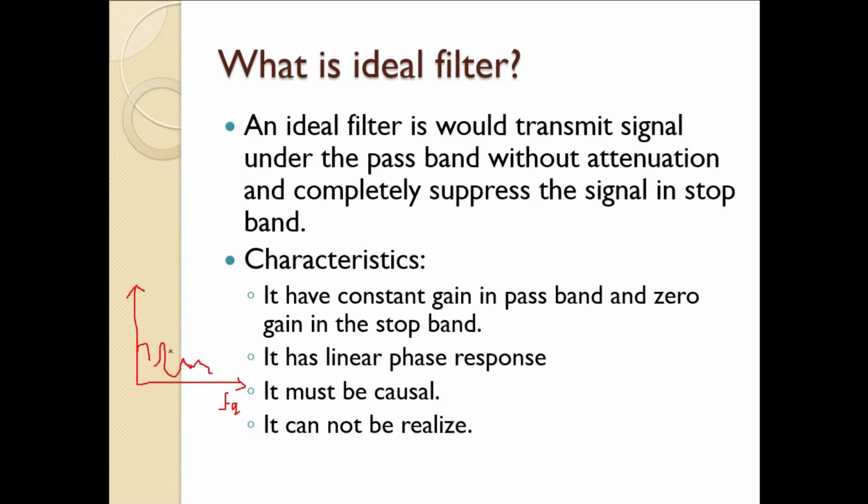In this range of frequency, we can cut off. For example, if the frequency is more than 5 Hertz, I don't want it. So I can set the frequency here and it will cut off like this. After the frequency of 5, which means 10, 11, 12 and more, we will cut off. This one we know as a low pass filter. This cut off area is where the ideal filter will sharply cut off without any attenuation. Here is the pass band, and the other side will be the attenuation, where the signal we don't want is the stop band.